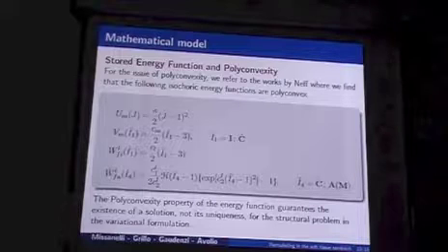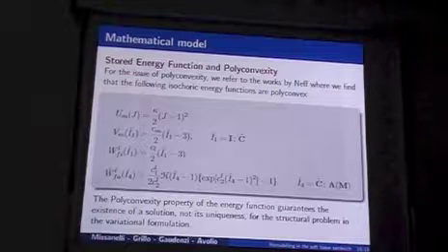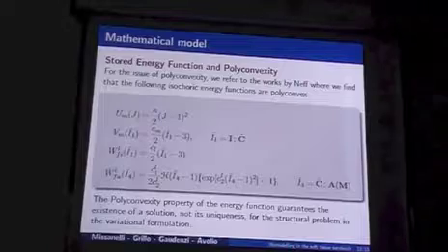The importance of polyconvexity is that we need the existence of a solution when we treat a structural problem like this one, a boundary value problem. It does not guarantee the uniqueness, so probably we can have some numerical instability, but the solution exists. At least one.